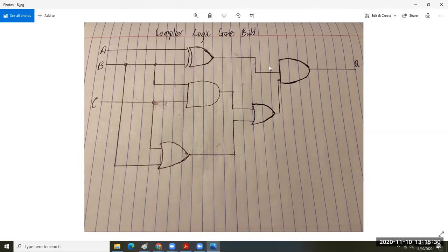The only thing I could offer, and this is really hard because I'm having to search here, might be this right here. If the line was run up and then looped on top and then continued, it would look like this wire is laid on top of the C, but that's a pretty trivial thing. The fact that there's a distinct dot means that's a junction, and they're two separate wires. The dot's really pronounced, so it's not like you get very confused. This is really good attention to detail. I like this.